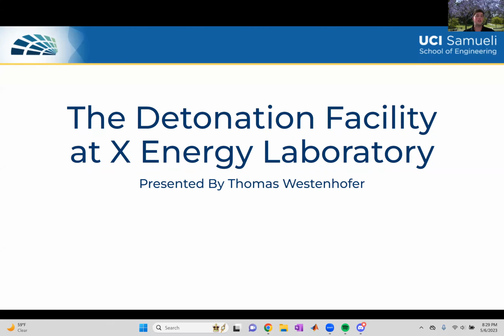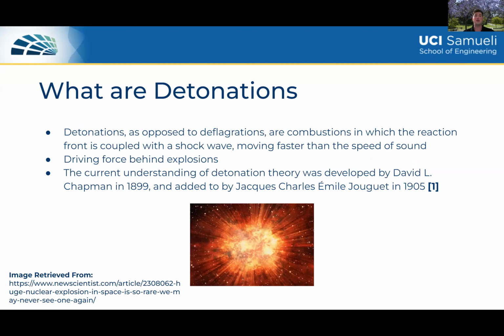When you hear the word detonation, you probably think of an explosion, which is correct. Detonations are the driving process behind an explosion. Essentially, a detonation is a combustion in which the flame front is moving at supersonic speed. This is because its reaction front is coupled with a shock wave.